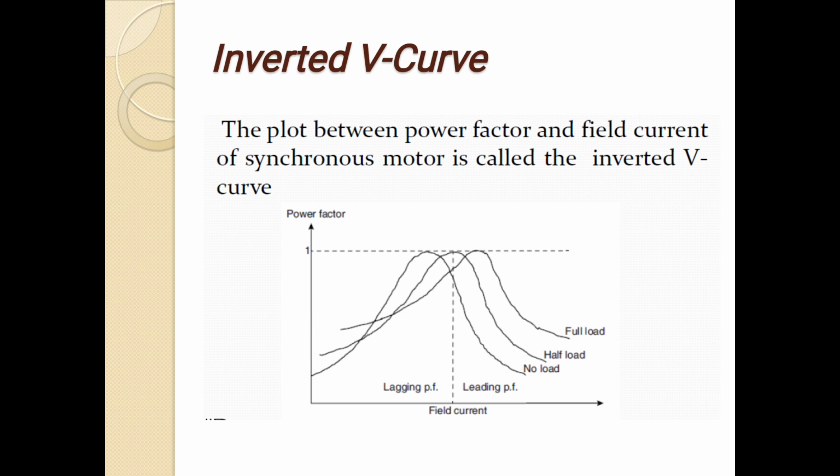The two wattmeters are used to measure the input of the motor. The voltmeter reading is the line voltage, so we find the line voltage in volts, line current in amps, W1 and W2 in watts, and the power factor.